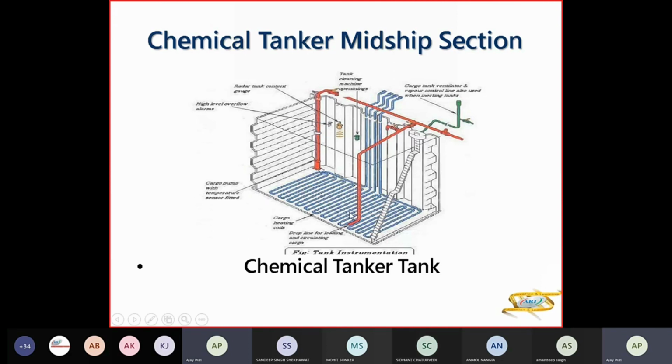Certain ships have recirculating and overhead heaters. In chemical tankers, the other type is overhead heaters. Those heaters are like large furnace-type structures on deck. Inside there are coils, and we recirculate whatever cargo is inside through them and then drop it back to the tank. So if your coil gets damaged, you can do maintenance on deck.